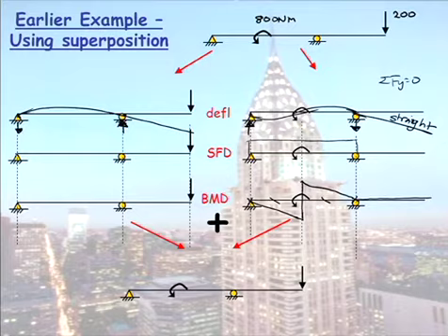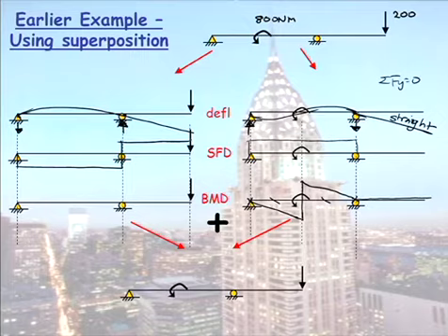So drawing now the shear force diagram, it will look like so. A negative is an upward slope, a positive is a downward slope. Our shear force is constant, our bending moment is therefore linear. Bending moment here is 0. At the pin support, bending moment at the cantilever is 0.